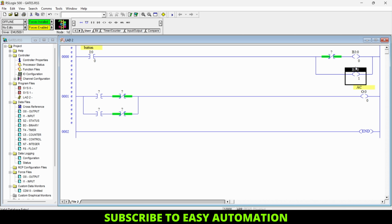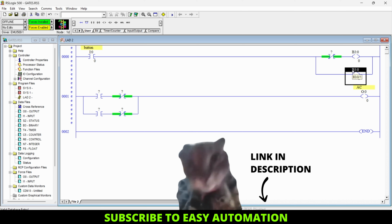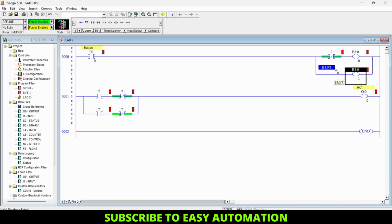If you don't know about memory bits, you can check out my previous video so that you can get the idea of how to use these memory bits. I will use this memory bit here for our NC contact, and at this memory bit we are going to get the trigger pulse.